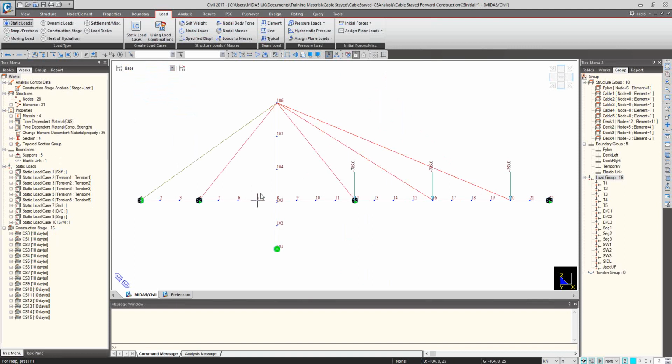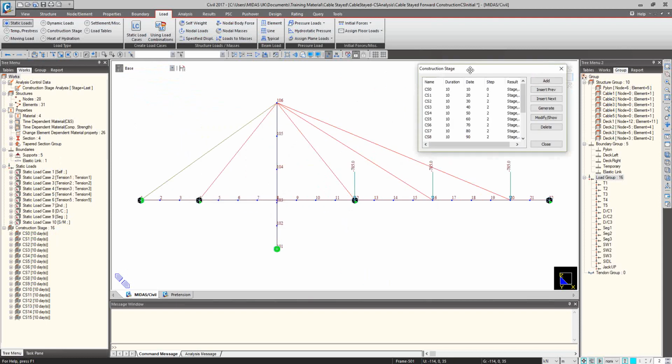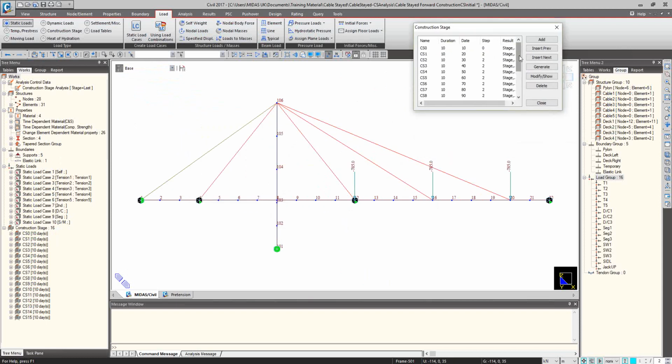So I want to build everything, and then I want to stress the tendons at the very end, which is unlikely, but just for showing you how even very big changes in the model can be done quite easily, I will do it. So as we said, tendon, let's say we want to stress tendon number 4 and 5 together.